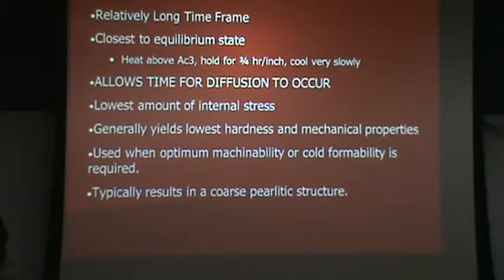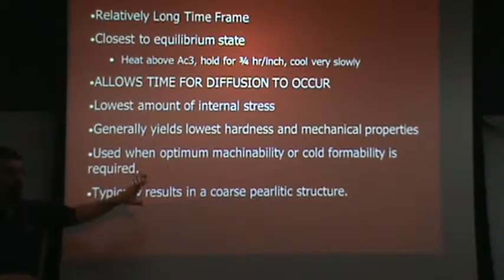This is an operation where diffusion is what's driving microstructure change. It's something that takes a long time. Typically, it's done by heating your product up and then shutting the furnace off and just leaving the furnace closed so that things can cool slowly over a long period of time. This one is the one time where you're going to see equilibrium behavior.